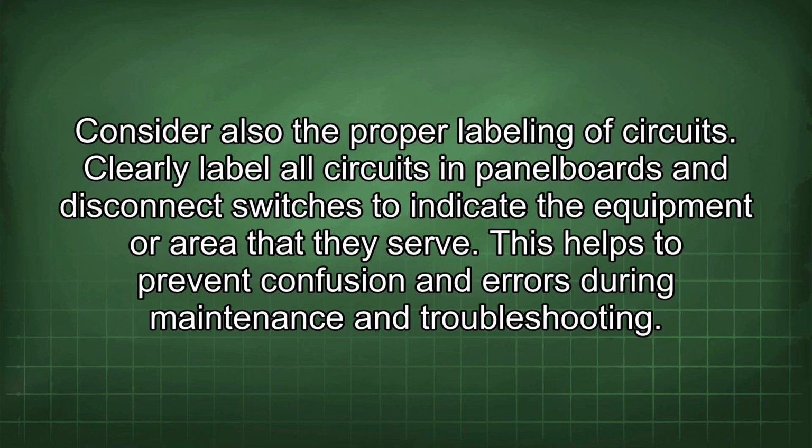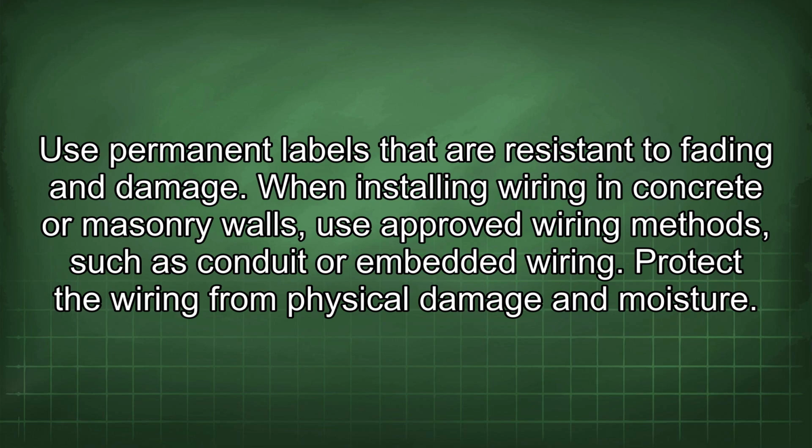Consider also the proper labeling of circuits. Clearly label all circuits, panel boards, and disconnect switches to indicate the equipment or area that they serve. This helps to prevent confusion and errors during maintenance and troubleshooting. Use permanent labels that are resistant to fading and damage.